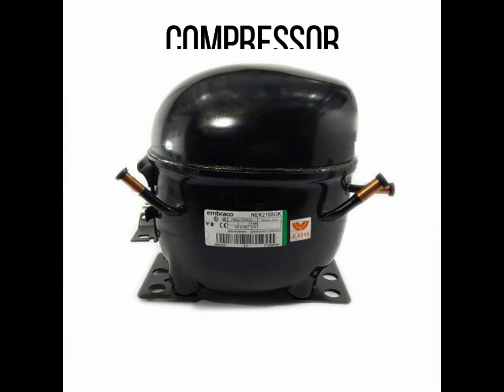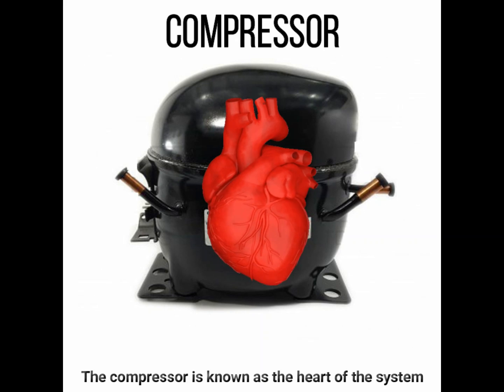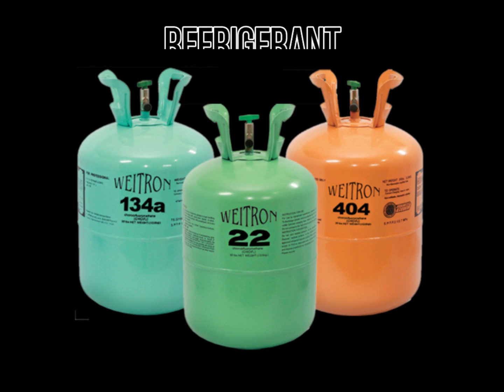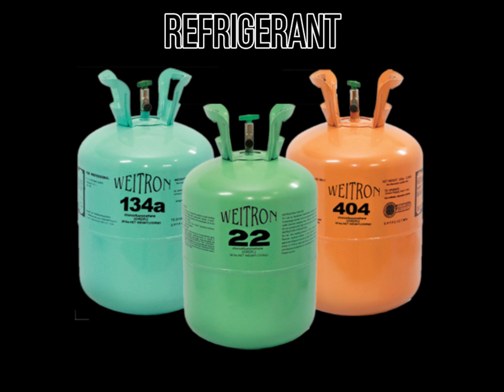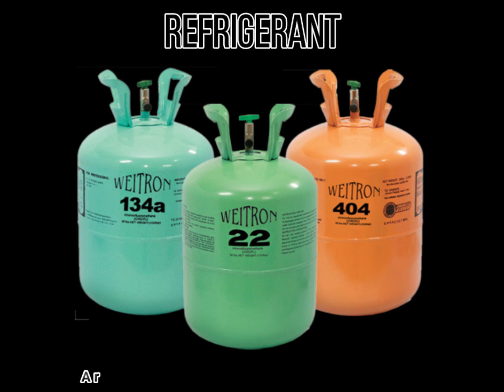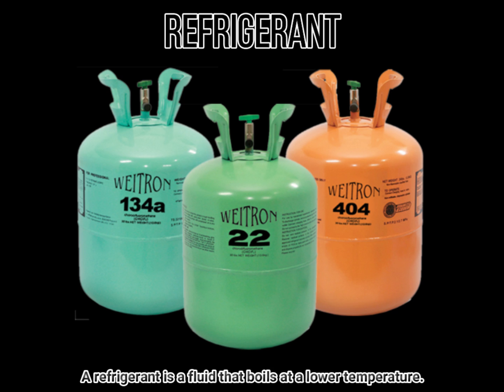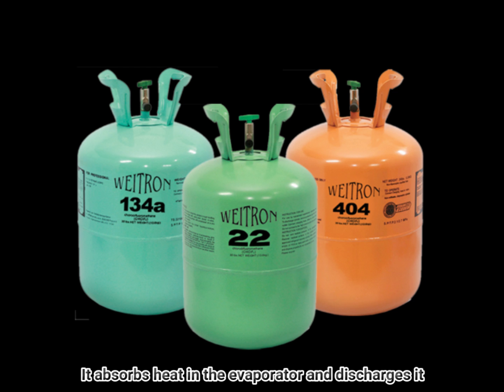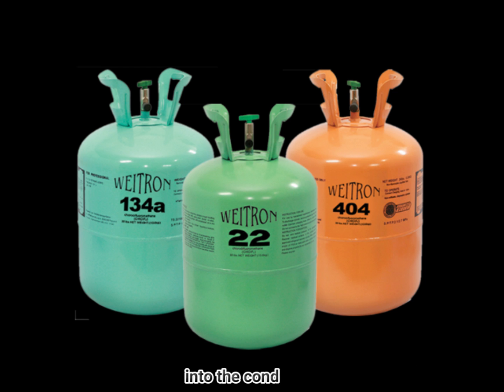First is the compressor. The compressor is known as the heart of the system. It compresses the low-pressure gas refrigerant to high-pressure gas refrigerant, also increasing its temperature. Second is the refrigerant. If the compressor is known as the heart of the system, the refrigerant is known as the blood of the system. A refrigerant is a fluid that boils at a lower temperature. It absorbs heat in the evaporator and discharges it into the condenser.